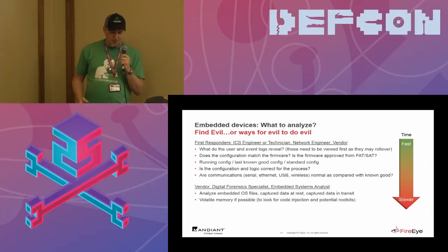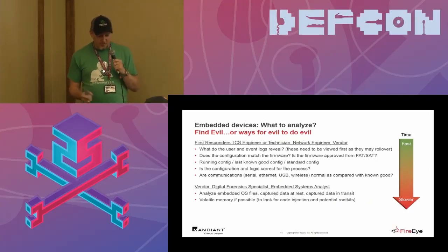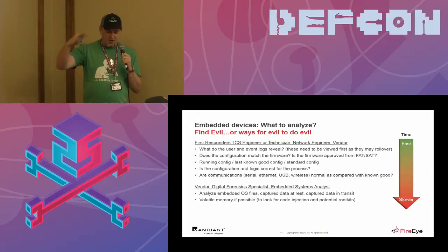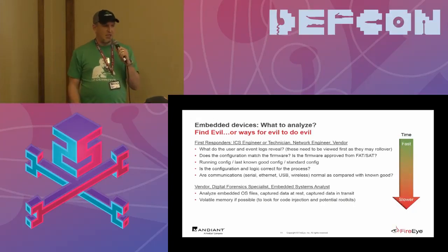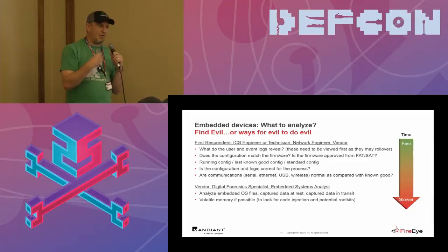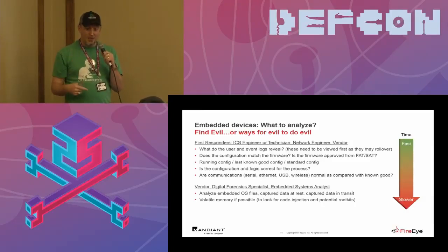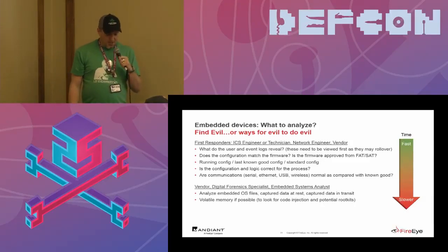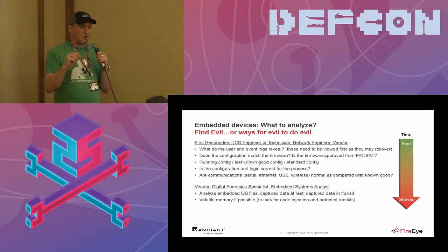What is the configuration? Does it match the firmware? Is it the firmware approved? Same thing. A lot of these things you've got to send a technician out there to collect, or an engineer or whoever. Is the configuration and logic correct for the process? So an engineer can look at the configuration and say, oh, someone made a mistake. That is not as fast as grabbing the configuration, but you've got to do a little analysis there. Are the communications normal? So you're going to have to look at a serial packet capture or an Ethernet packet capture, and that takes a little bit more time.